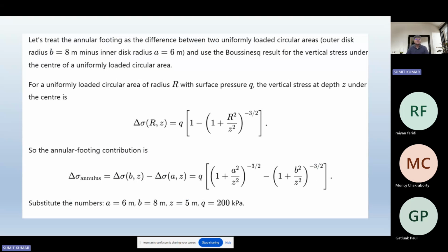The solution says, let's treat the annular footing as a difference between two uniformly loaded circular areas: outer disk radius b equal to 8 meter minus the inner disk radius a equal to 6 meter. Now we use the Boussinesq result for the vertical stress under the center of a uniformly loaded circular area. For a uniformly loaded circular area of radius R with surface pressure q, the vertical stress at depth Z under the center is given as q into [1 by (1 plus R square by Z square)] to the power 3 by 2, with a minus sign as 1 minus that. So for the annular footing contribution, delta sigma annulus becomes...